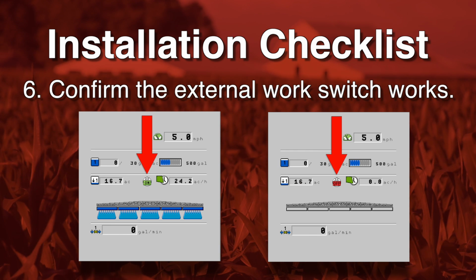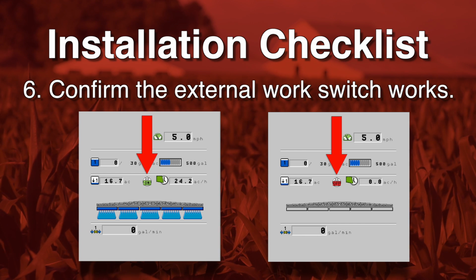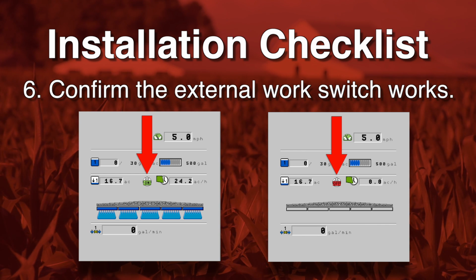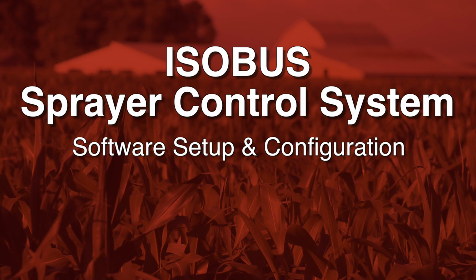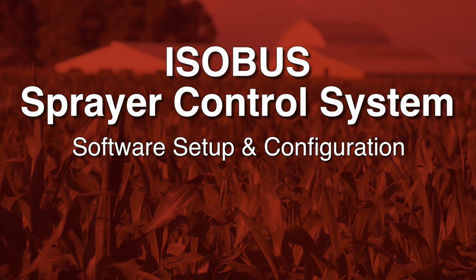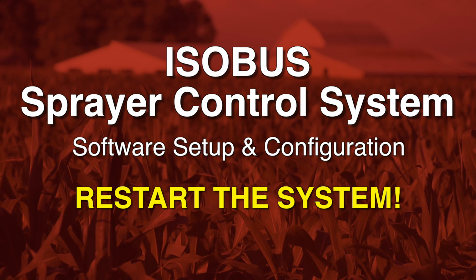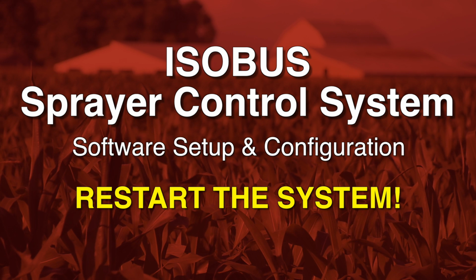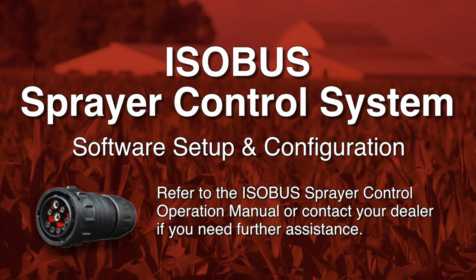Finally, if a foot switch or external work switch is installed, verify that the switch is calibrating correctly in the universal terminal. Sections should be turned on and off with the engagement of this switch. This completes the software setup and configuration of the ISOBUS sprayer control system. You need to restart the system for the setup and configuration settings to now take effect. Refer to the operation manual or contact your dealer if you need further assistance.